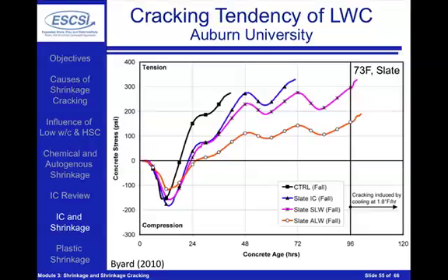What we can see here is they were going through a case where they were essentially starting to talk about what happens when you are casting a bridge deck and you're having the daily thermal cycles for a fall type of construction environment. And here what you can see is the plain concrete shown in black, the internally cured concrete shown in the bluish color. What you can notice here is a later date of cracking inside of the system. The main reason here is because you're reducing some of the stresses that are developing in the system.